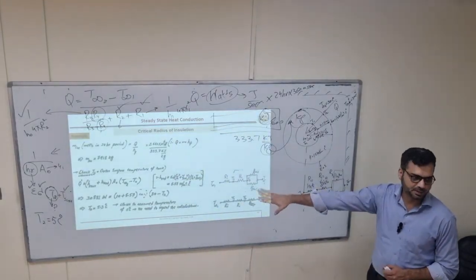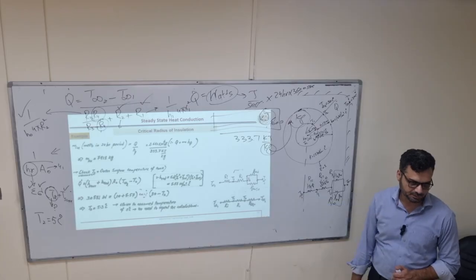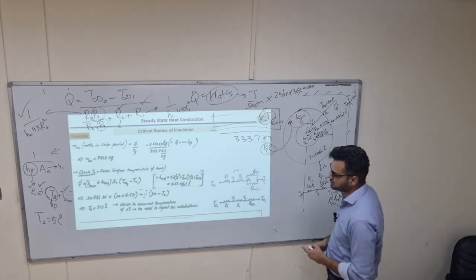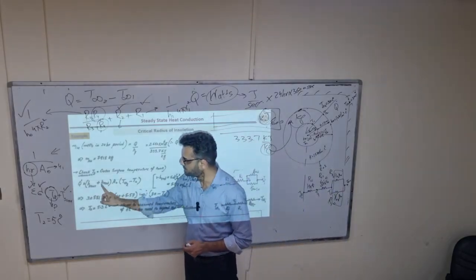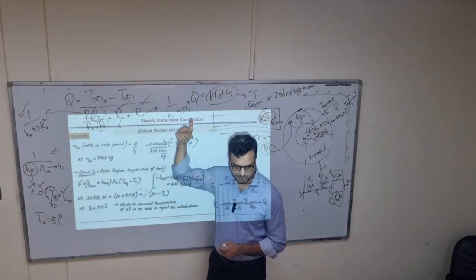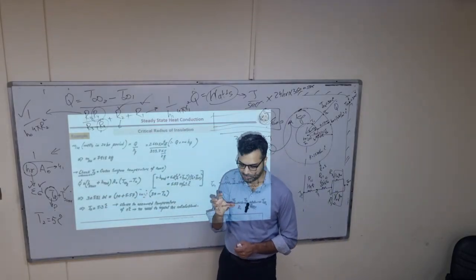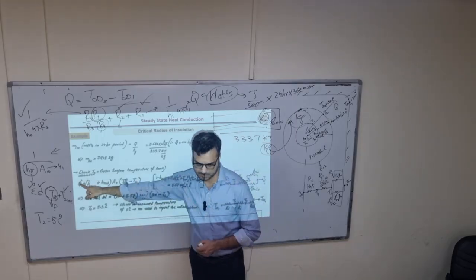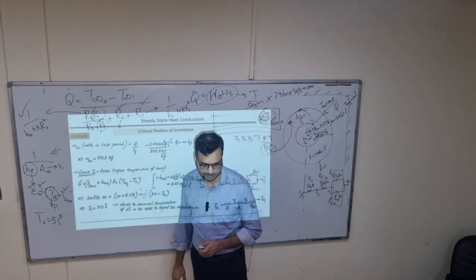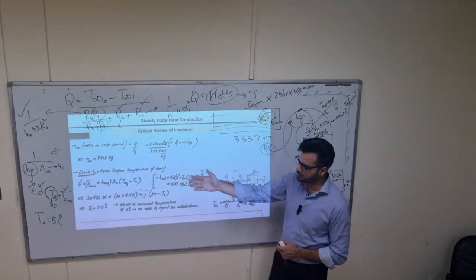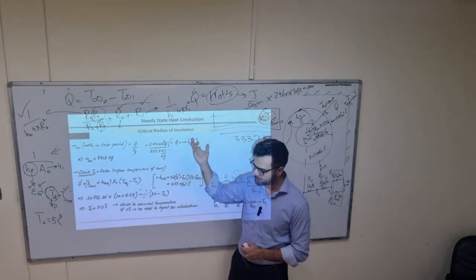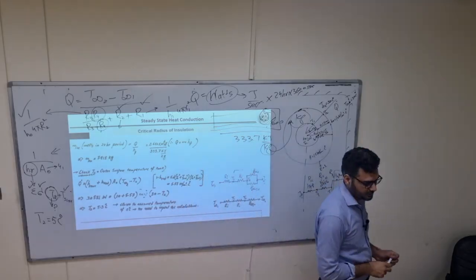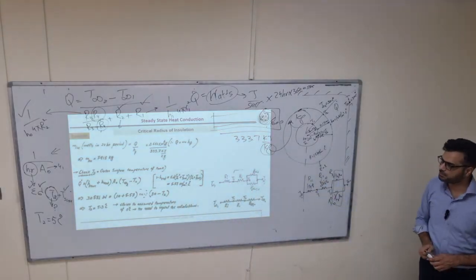So he will stop here, but if it is too different, then you have to do another iteration. He's using the same radiative heat transfer coefficient, which he used earlier with 5, and now using that 5, he is calculating T2 from this equation as an unknown. If you choose, you can try it with 10. At the end, you should end up near 5. And you can easily program it.